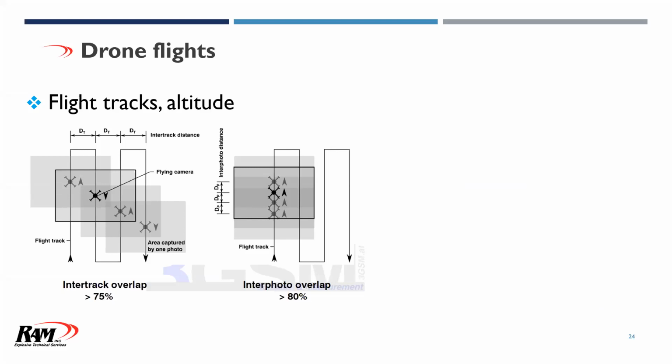And that's where a lot of these softwares differ. Some of these GIS type ortho packages will paint over areas where there's gaps. In this type of software that's designed specifically for blasting, if it doesn't have adequate coverage from those images, it's going to leave a hole in your model.